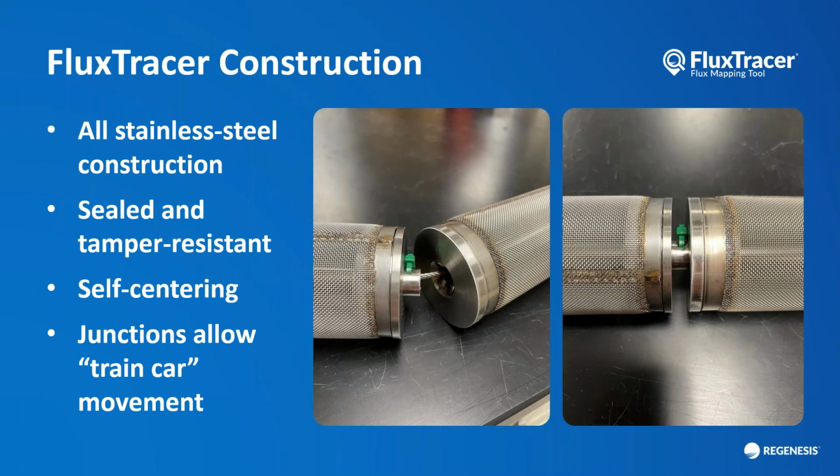A little bit more about the construction of the devices. They're all stainless steel, so the entire device that goes into the well is stainless steel. It's filled, like we said, with a granular activated carbon that's got these leachable tracers that are preloaded onto them to measure the groundwater flow.